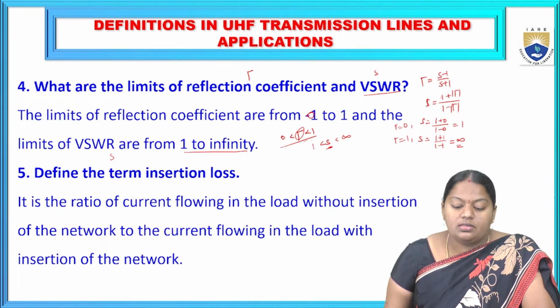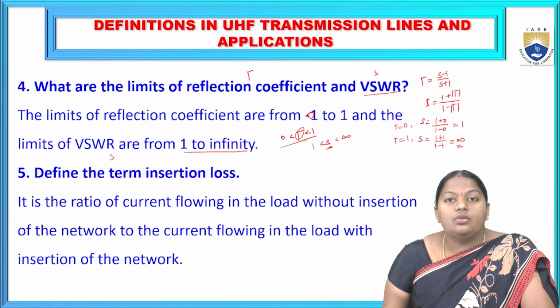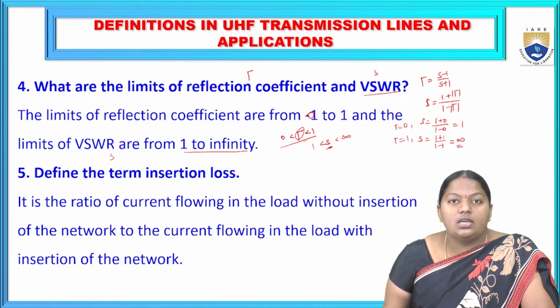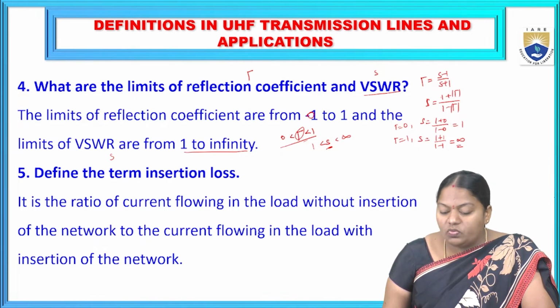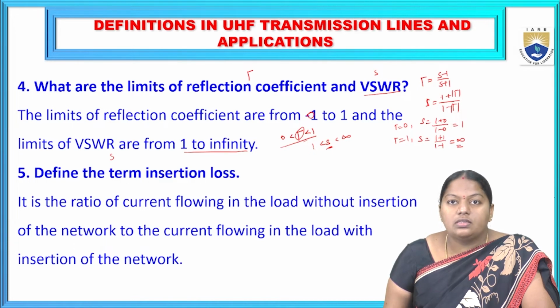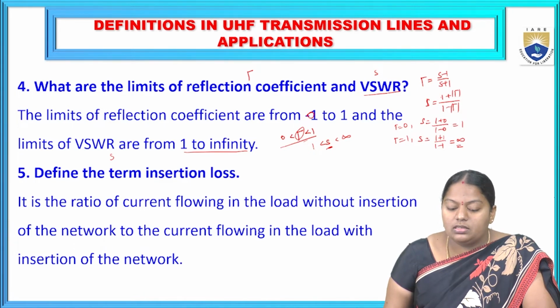And insertion loss. In order to define insertion loss, we need to consider the ratio of the current flowing in the load without inserting the network to the current flowing through the load with insertion of the network. If any difference exists between the two, then that gives us the insertion loss.